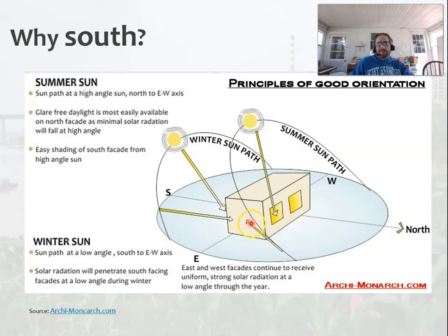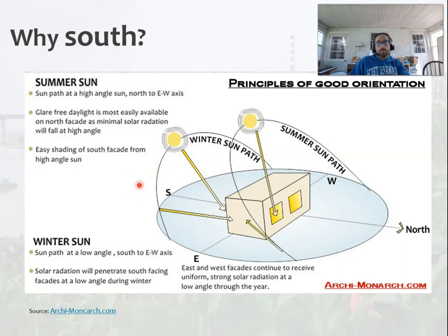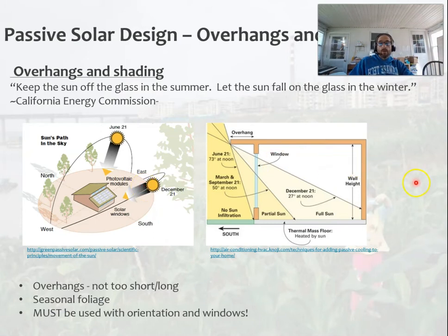So, probably by 3 or 4 hours after sunrise, whenever that is, it'll be south and then it'll still peak in the south. So the hottest sun is always due south of you. And almost the entire year, the sun is going to be south-ish. So the sun spends almost all its time south of us. So if we want to capture the sunlight, we want our building to be faced toward the sunlight, and that's why we want to be faced south.